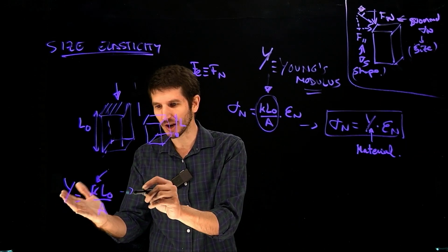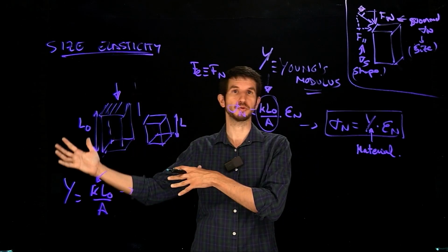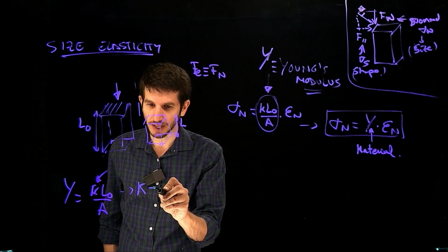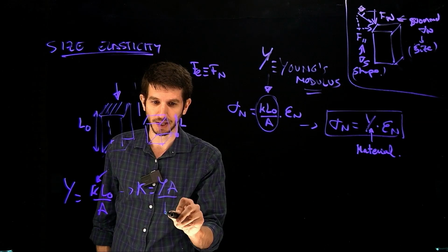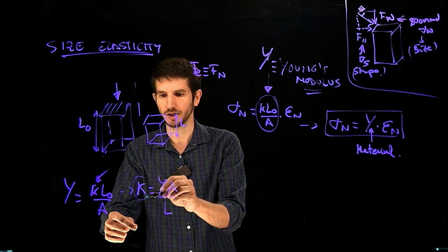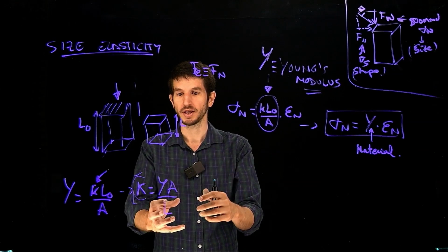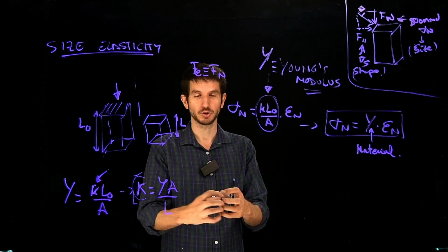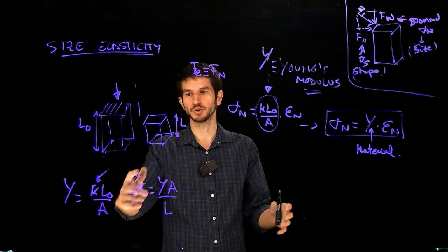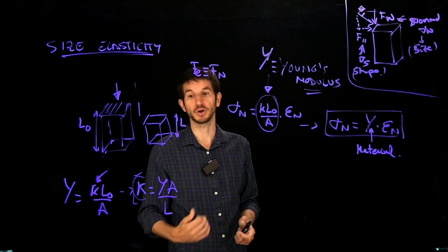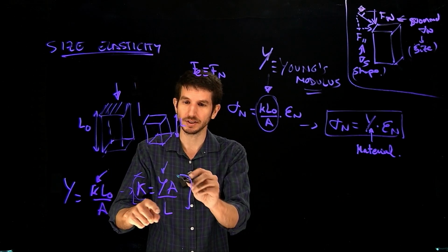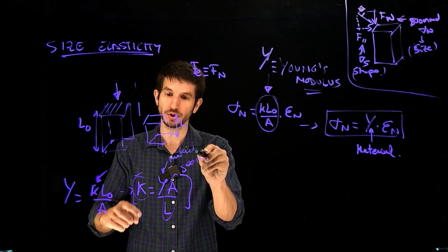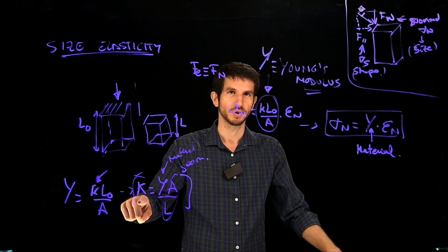The way we derived it is because I wanted to draw from the things that we introduced before. But in reality, we should go from here to Hooke's law, not the other way around. If we do that, we can solve for K, and we're going to see that it is Young's modulus times A divided by length. And this makes sense. The shorter a spring is, the more difficult it is to stretch it. The larger the area, the more difficult it's going to be, the stronger the spring constant. So here this component is the geometry, and this one is the material.